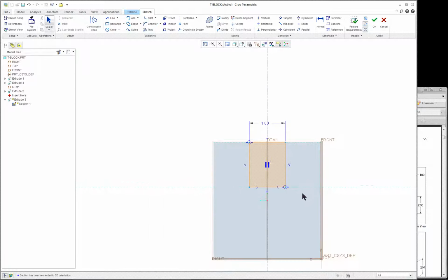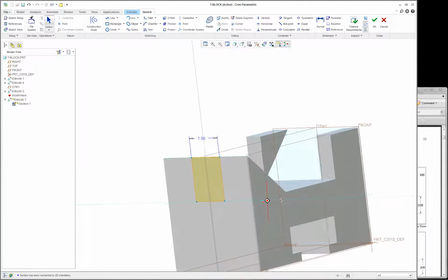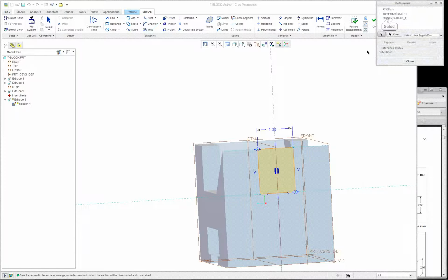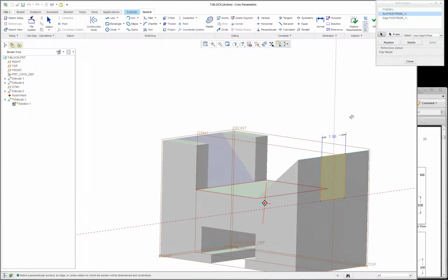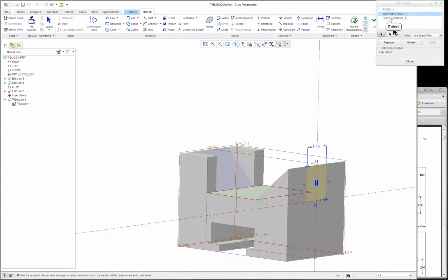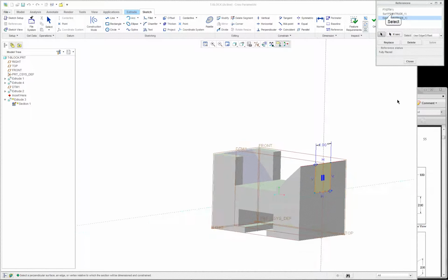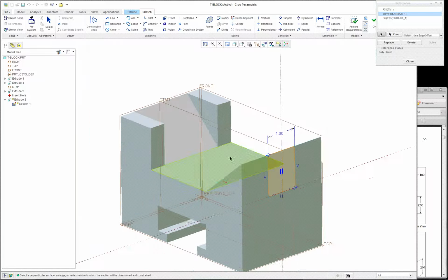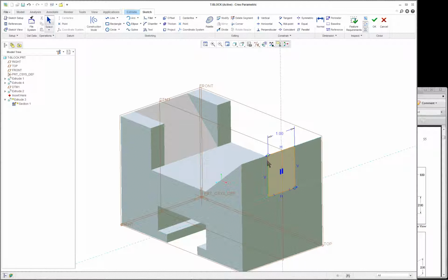And the most important thing was identifying the references. So there is a reference along the top and one at the bottom. So references here, you can see that those have been selected. We have the top edge, and we have the whole surface over here. So I actually rotated the model and selected this as the reference. Then used a rectangle, and the rectangle will give you your symmetry easier. I'll cancel that one.